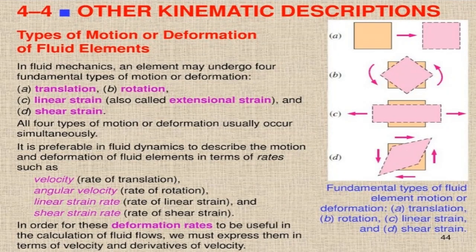But when it comes to fluid particles, because fluid particles also have velocity, we do not deal with the translation, rotation, linear strain, or shear strain directly, but we deal with the time rate of change of them.